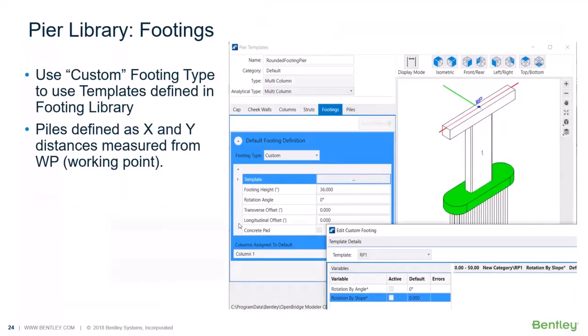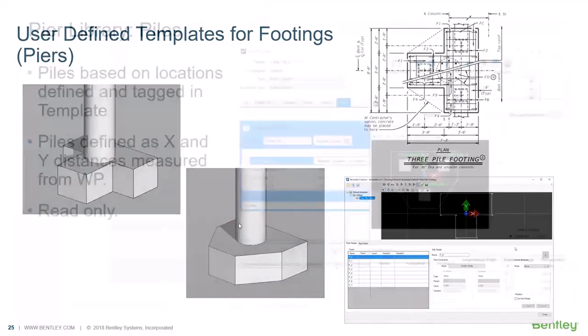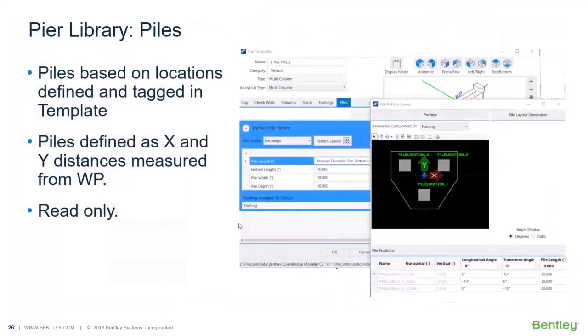In this case, it was shape oval footing, right? Then after that, the height, the pile locations and the pattern of the piles are all managed through a dialog box. So any particular shape that you may want, it's a matter of drawing the 2D template for that, right? Again, before, the workaround was to just cut off the footings, losing the parametrics in the process. So now it's all parametric, right?